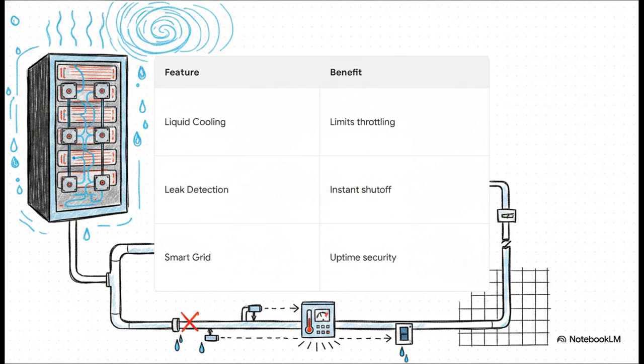SCC extends way beyond traditional server metrics here, giving you deep liquid cooling oversight. We're talking everything from the facility's main water loop right down to the microscopic cold plate sitting directly on the silicon chips. It's constantly monitoring coolant flow, pressure, and temperature telemetry. This lets the system spot thermal hotspots and intervene way before they throttle your processing performance. It's essentially an automated, policy-driven safety net for your massive AI investments.